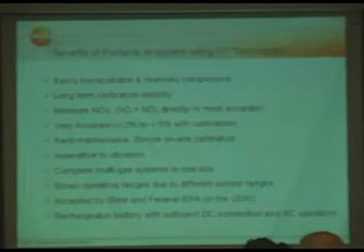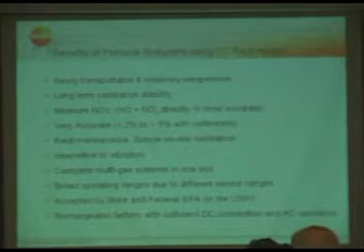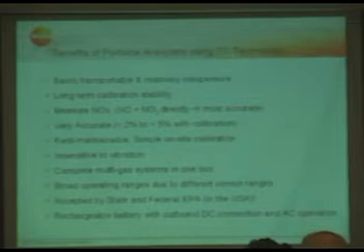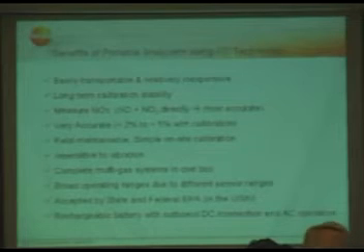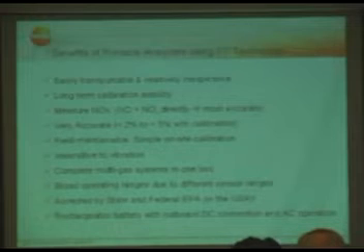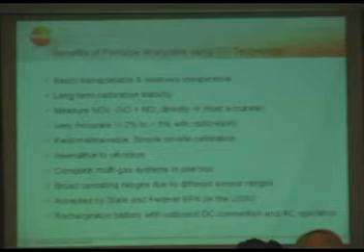That means our recommendation is you can send in the analyzer once a year, where in the service department the calibration is taking place. That means the sensors, if they are no more correct, will be readjusted. Or if required, you can also readjust or calibrate our analyzers in the field by yourself. If you have the different calibration gases with you, you can do the calibration without any problem. And it will be stored in the analyzer, and you can do a printout of the calibration date and the concentration and the drift and everything.